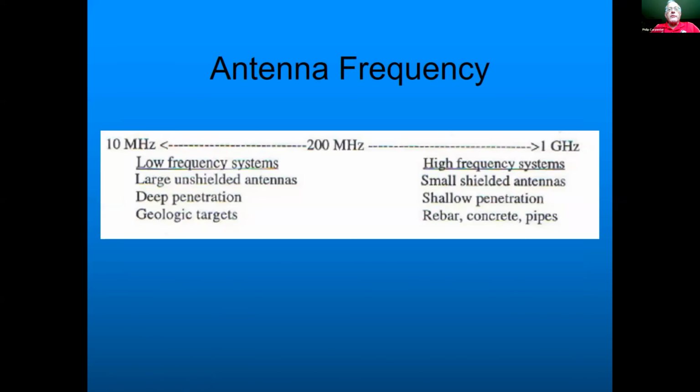Okay, let's get on the radar. GPR, ground penetrating radar, is one of my favorite methods. Just some background information on GPR: it's very, very important to have the correct frequency for your system.